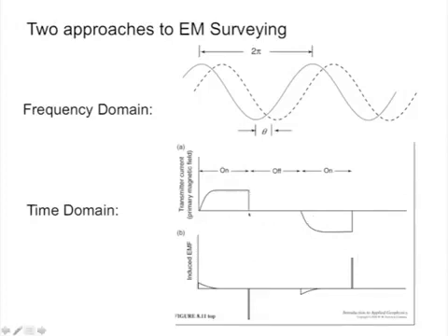It is possible to cut off a current very, very fast, but it's harder to instantly start a current in our transmitter coil. So we've got to ramp it up. All right, and then we cut it off. And we go in opposite directions because we want to avoid battery effects and just measure that fundamental resistivity property, right? That fundamental conductivity property that's the same whether it goes one way or the other.